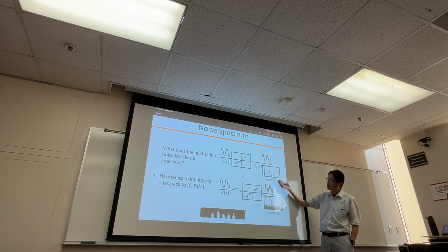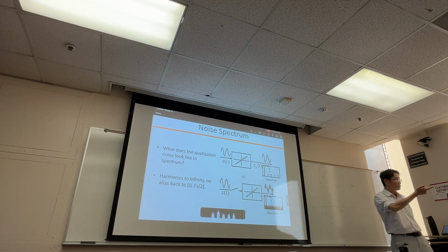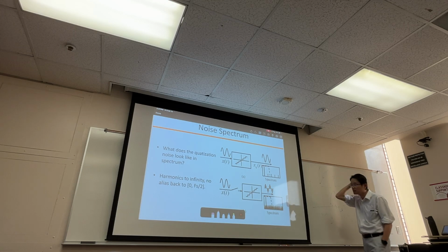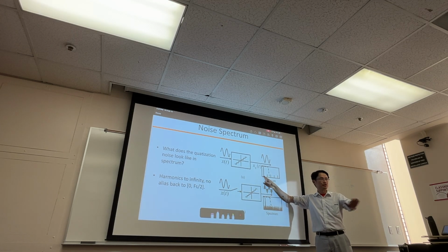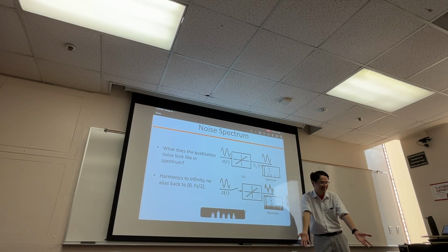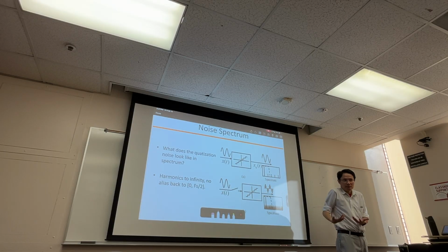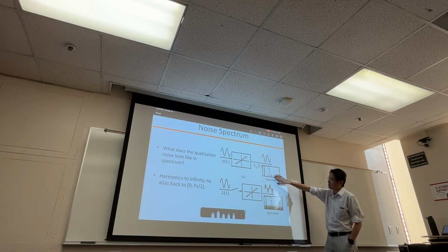If you look at the spectrum, do I see the input? Let's say this is a 127 Hertz sine wave. Do I see the input? Definitely. Yes, you have to. That's the first thing that you have to see. Inject a sine wave and you see nothing out? What's going on? Your circuit is not working, or you forgot to power up. It's still powered down, right? So you see nothing.